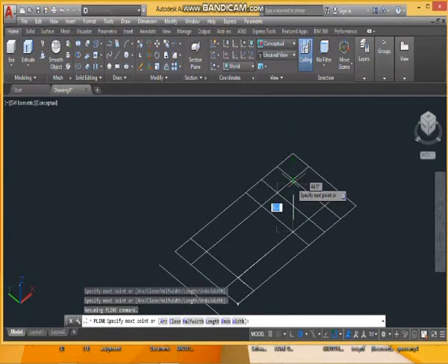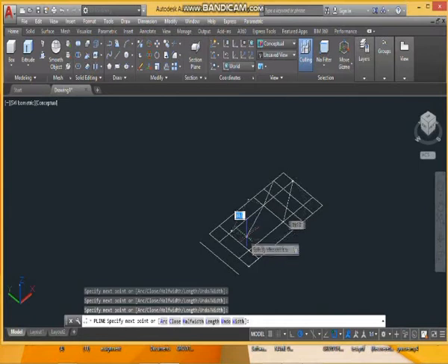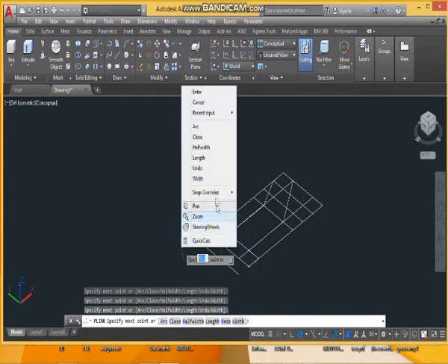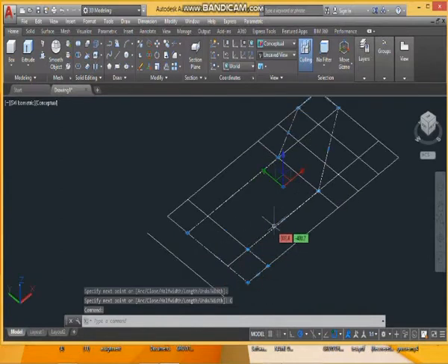Now we are using the polyline to pick and then come out with something that looks like the half section of the plate. We close it so that we can have a plane figure that can easily be rotated into a solid.